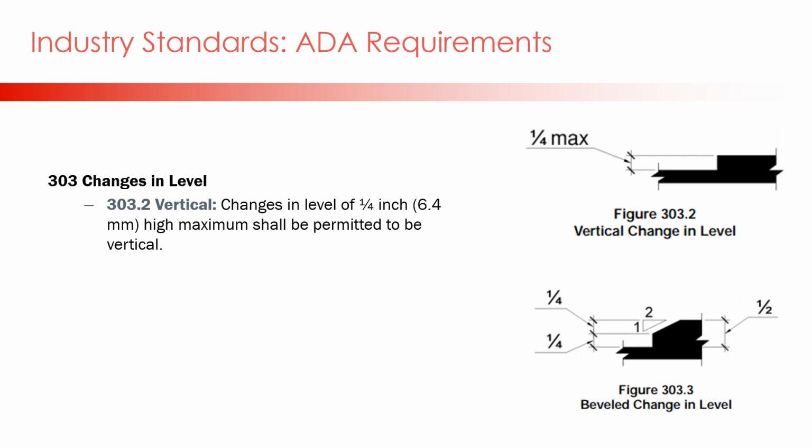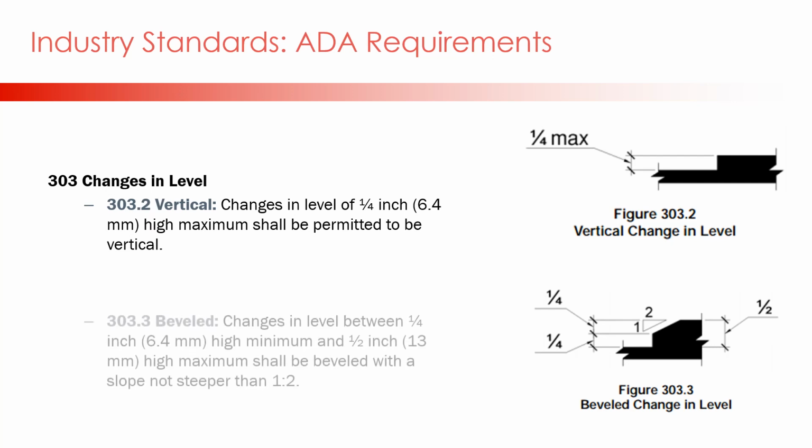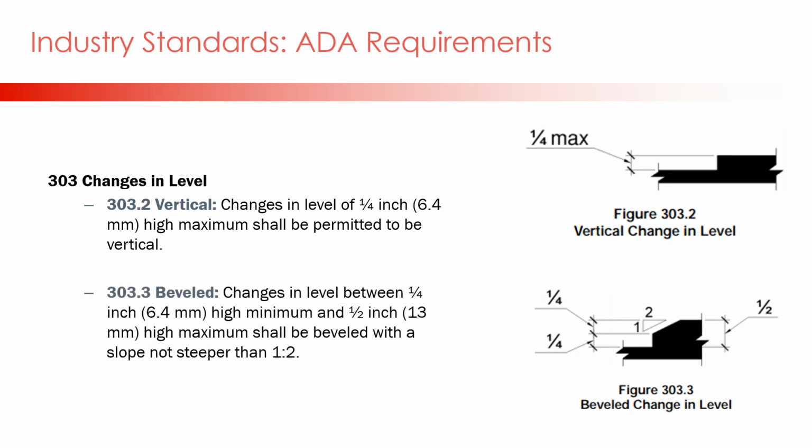Changes in level between 1/4 and 1/2 inch shall be beveled with a slope not steeper than 1 to 2. In layman's terms, it means a 1/4 inch change from one surface to the other is acceptable without any accommodations. If the change in level is greater than 1/4 inch, a slope is required.